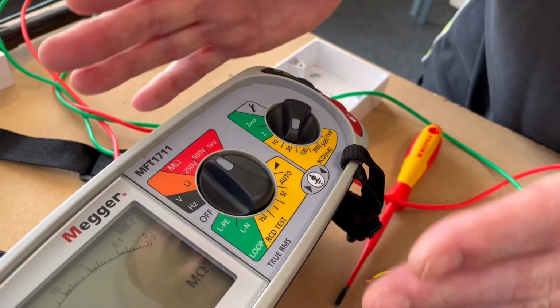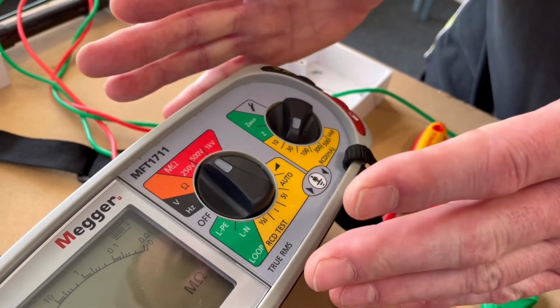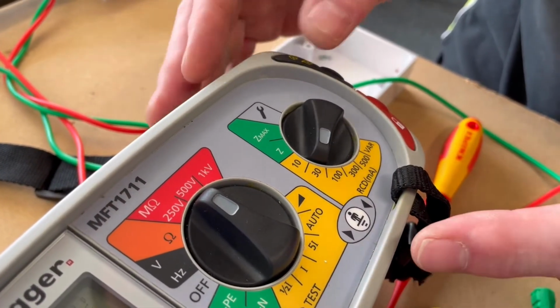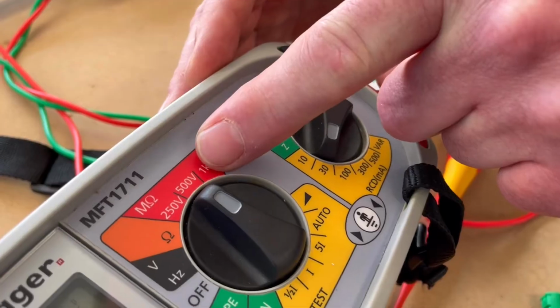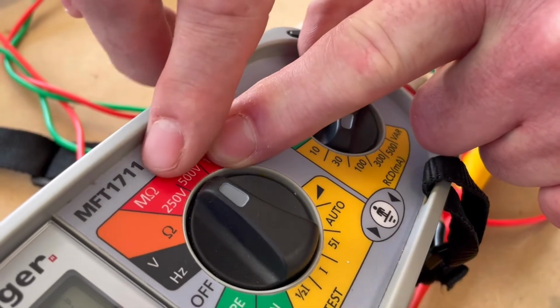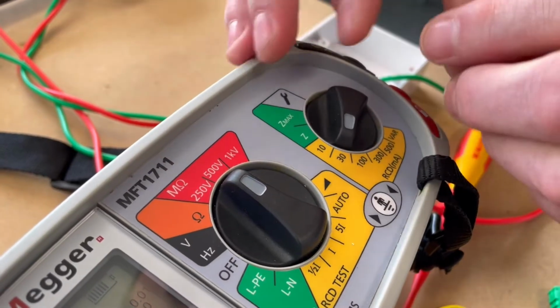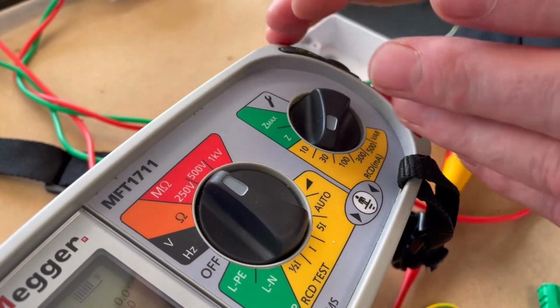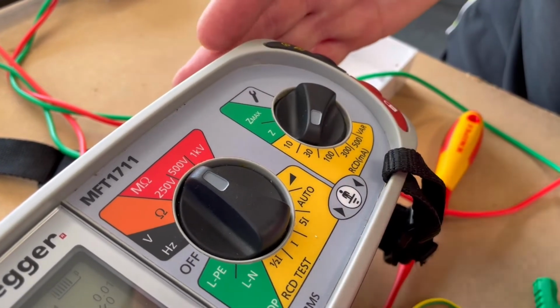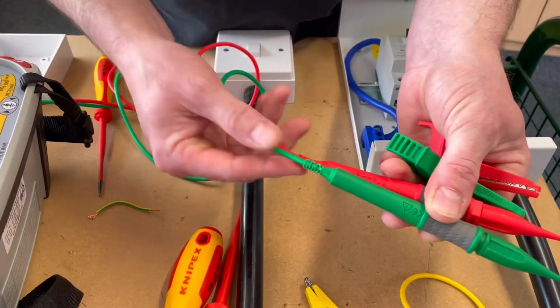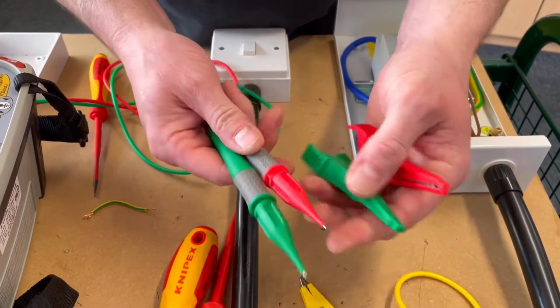I've done a separate video explaining about insulation resistance and length of conductors, and again I'll leave a link for that video if you haven't already seen it. So for this test, it's 500 volts DC. We're in the megohm scale, and we're going to be expecting a reading very, very high, possibly an infinity reading, or one greater than the machine can read, as we measure its insulation resistance. Just to prove these leads haven't been damaged during the first test, I'm going to short them together on this scale.